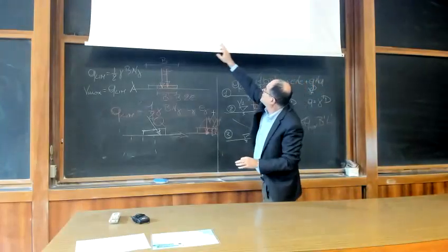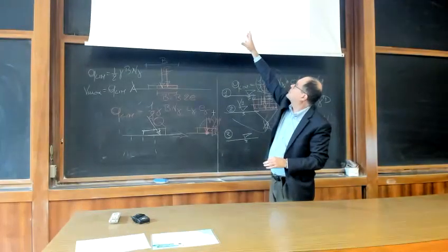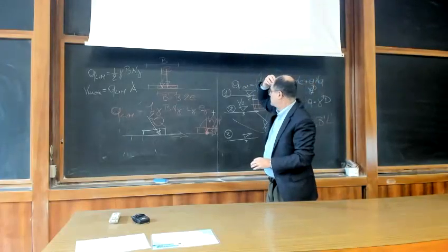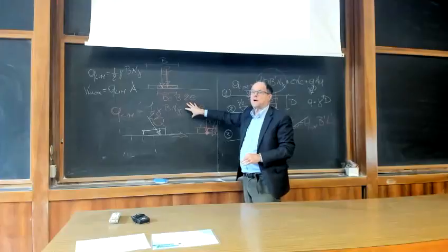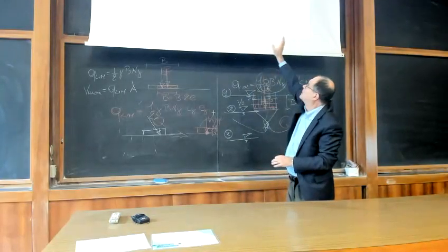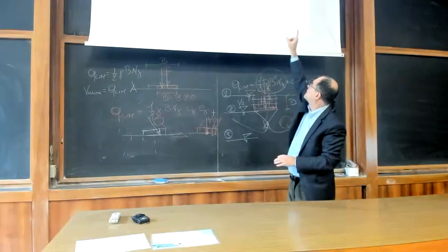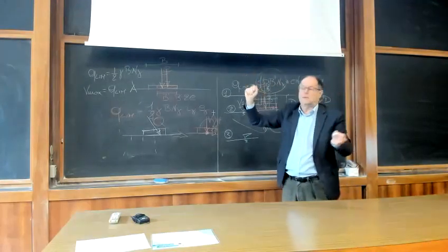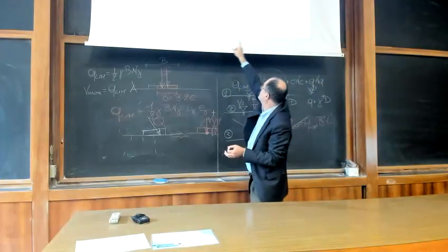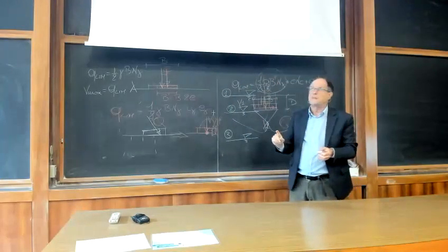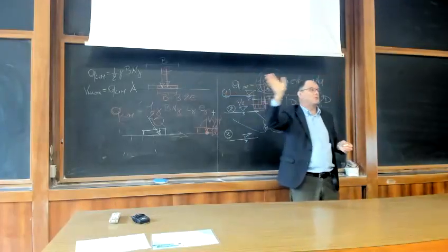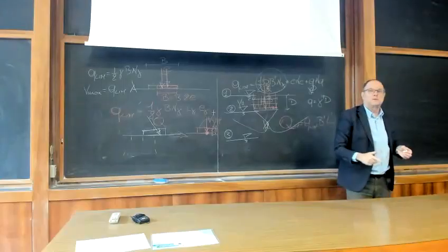Now, you see here the situation of an inclined resultant, Q. Instead of considering an I gamma, which is a function of the angle alpha, or H over V, you just plot the Brinch Hansen inclination factors in terms of H over V max versus V over V max. And you see, you end up with a curve which looks very similar to the red line we had in the previous slide.